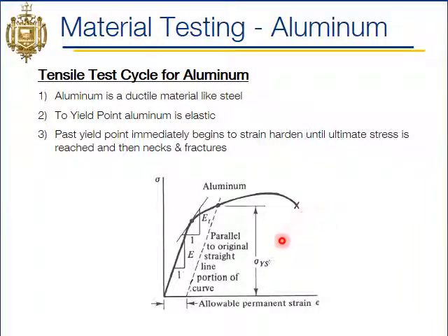One thing that's great to see on this graph here is this correlation of Young's modulus when we pass the yield point. So here's our aluminum yield point. Right, so let's say we stressed a material to some stress beyond aluminum's yield point, so right here, and let's say we take the stress off right here.